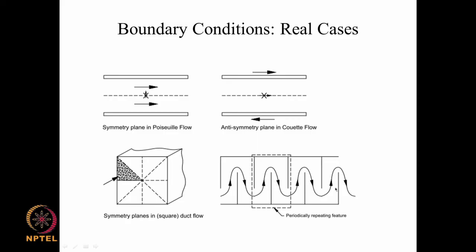For example, in a heat exchanger you can have these kind of baffle plates, and flow comes in like this and then goes out like this. So these kind of baffle plates are used to maintain good circulation of the flow so that there is no bypassing and things like that. So in such the geometry of the tube arrangement and all that can be quite complicated.